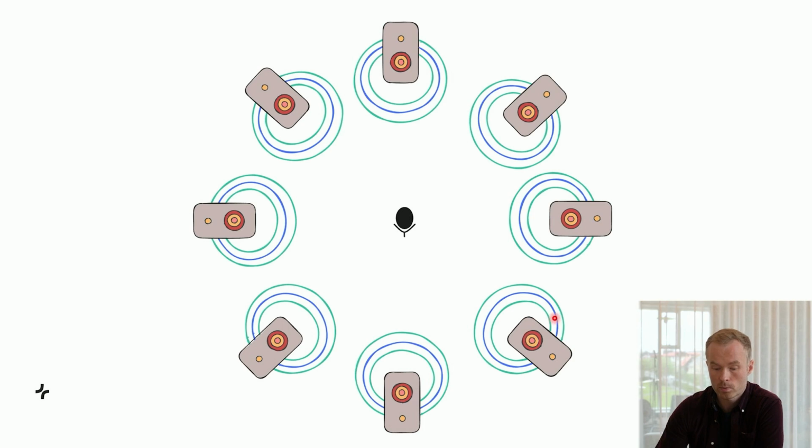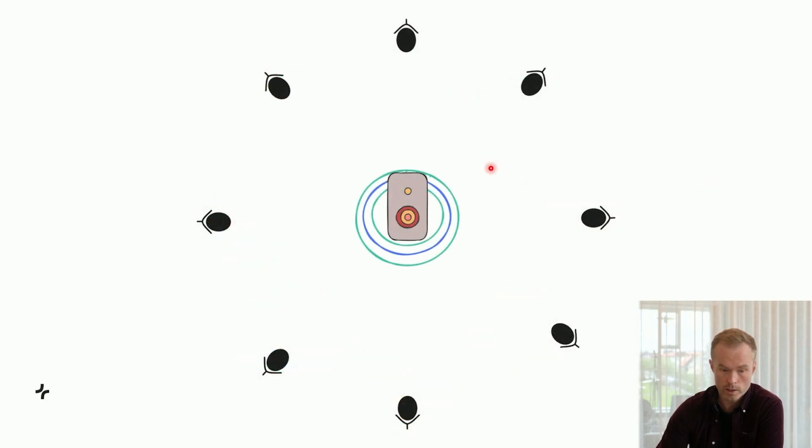So in a simulation setup, theoretically we would need to do individual source simulations from hundreds of different angles, which would become very expensive because these are many simulations. But thankfully in wave physics we have a thing called reciprocity, which means that this scenario that we have in this illustration is equivalent to this one here, where we're listening at hundreds of different angles and we only play the sound source from the intended microphone locations. So this is what we do in the simulation. We do a simulation from the center, from the actual microphones on the device, and listen at a sphere around the device.